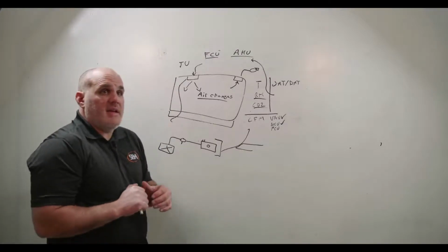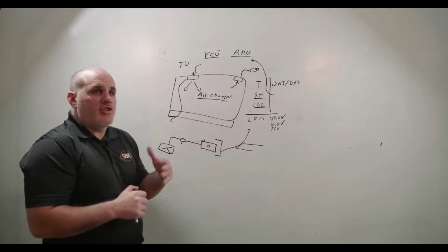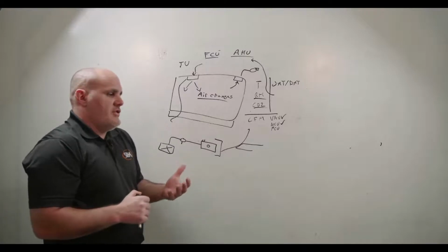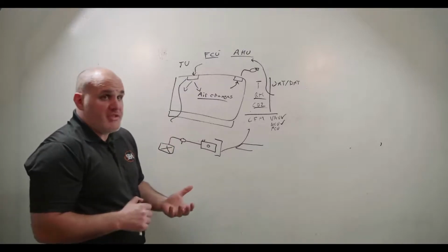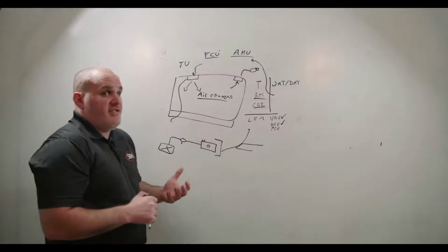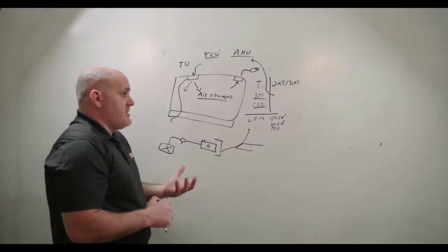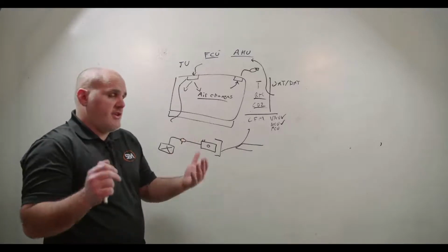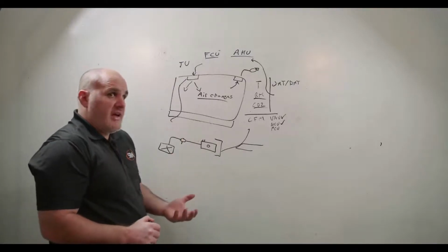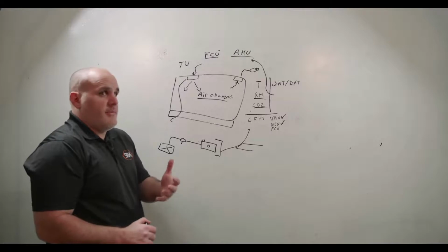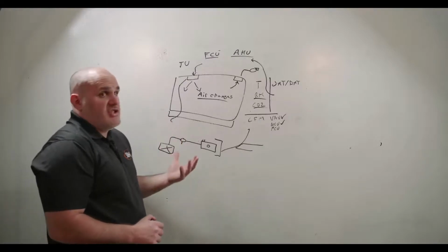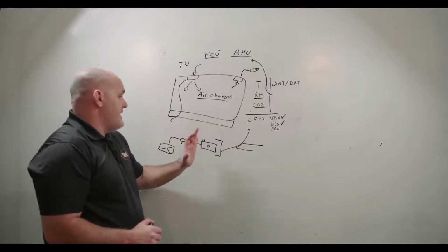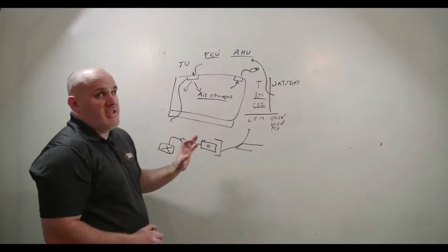sometimes it can be a tenant improvement, and you go and you improve the space, and you start using it for computers now, whereas it wasn't designed for that heat load, and you can have issues like that. Or maybe they redesign the space and now you've got giant southern exposed windows that aren't glazed, aren't properly shielded from the solar gain. That can be an issue, but those are outliers. Normally, it is almost always something to do with CFM.